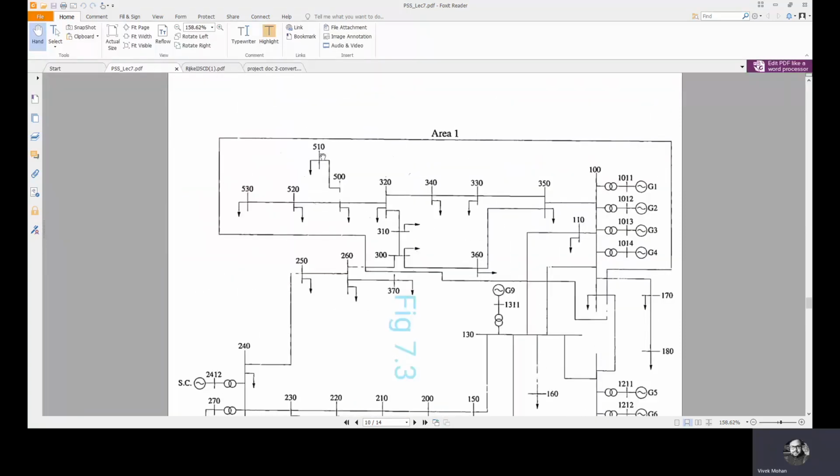Similarly, we are increasing the load at different buses, step by step increments. Now, according to the increment in active power at these buses, the active power at source should also be increased so that the power balance is maintained.